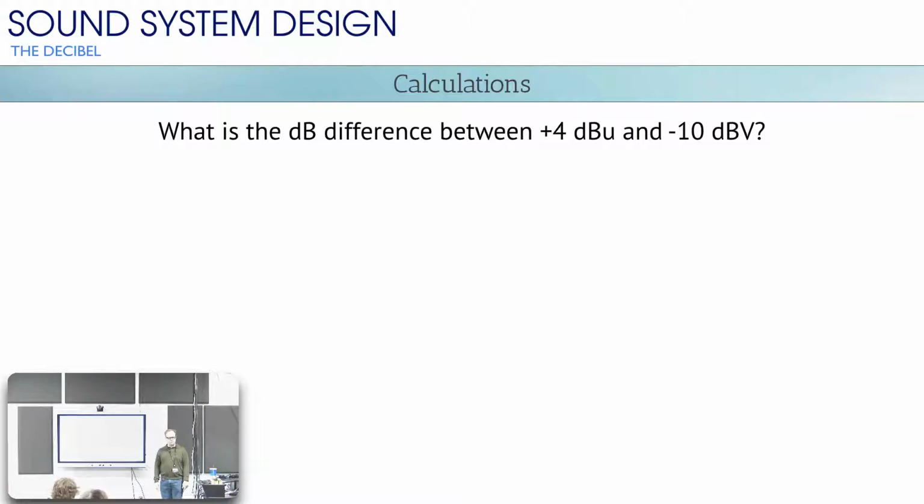what would the dB difference be between them? It's the same CD. You're not doing anything different with the gain knobs or anything on the mixing console. There will be a difference in output between those two things because consumer-grade equipment outputs a lower nominal operating voltage than professional equipment does. Right? Professional equipment does 1.23 volts nominal. Consumer-grade equipment does 0.316 volts nominal.